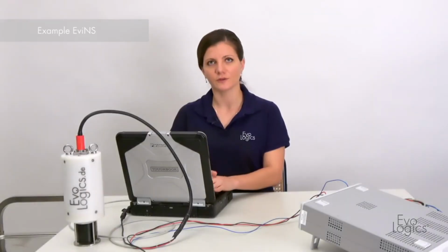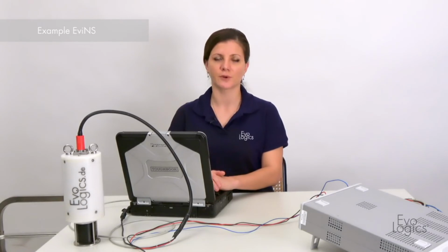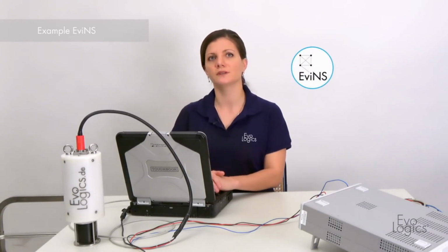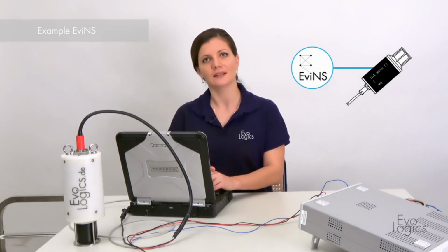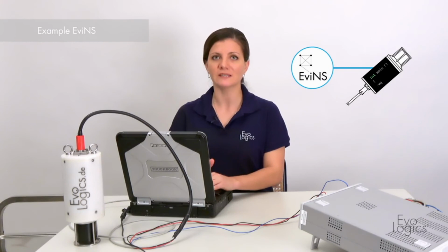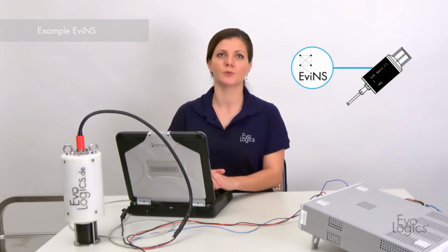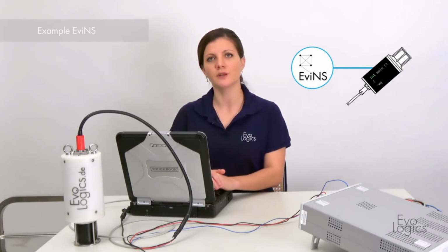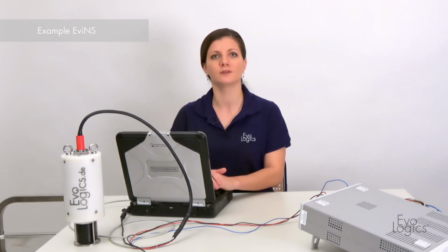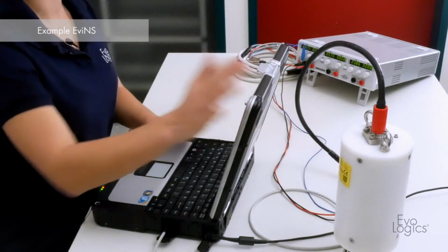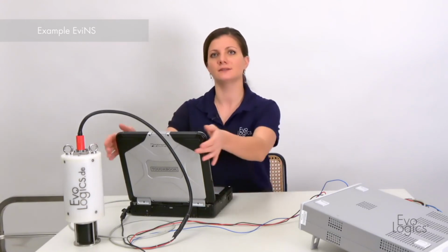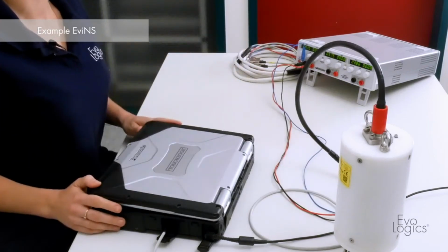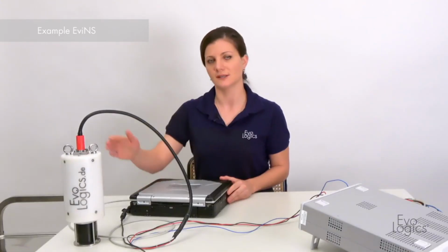In the last video, we made an introduction to the EvoLogics framework Evo. The framework can also be run inside the sandbox. But why is it interesting for a developer to run it in the sandbox? The answer is simple: less time and effort. After Evo-based media access and routing protocols were tested in the lab, running them in real water conditions would require us to interface each modem in the network with its own host PC. Using the sandbox eliminates the need for extra infrastructure, because Evo runs on the virtual machine inside the modem.